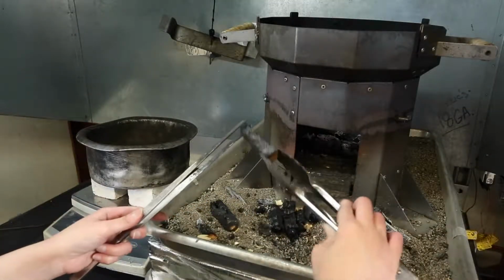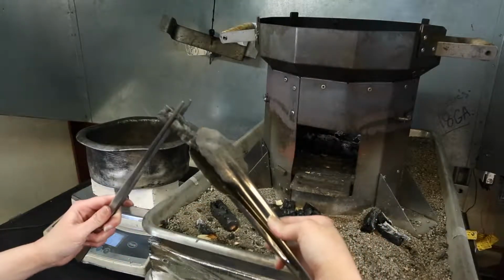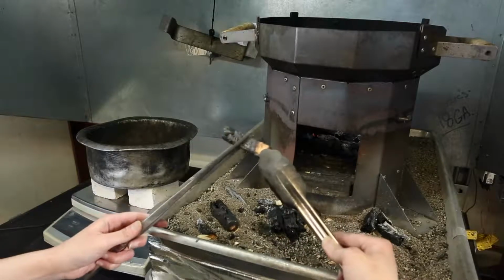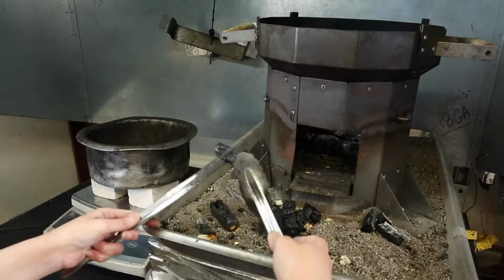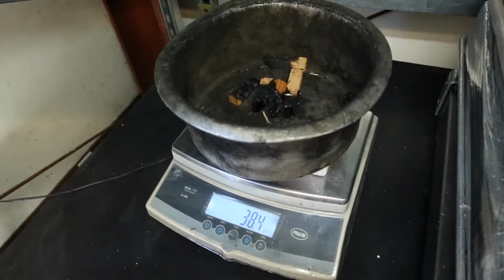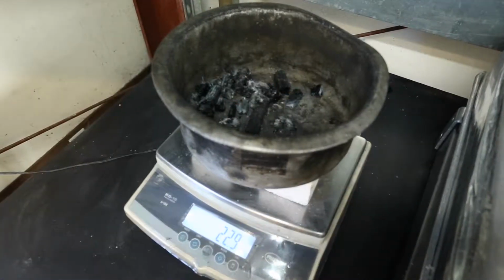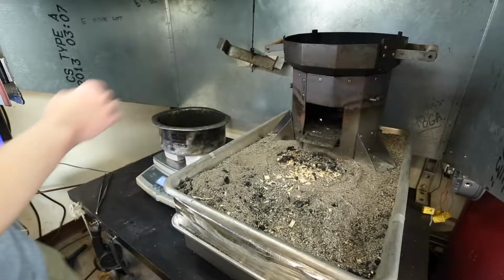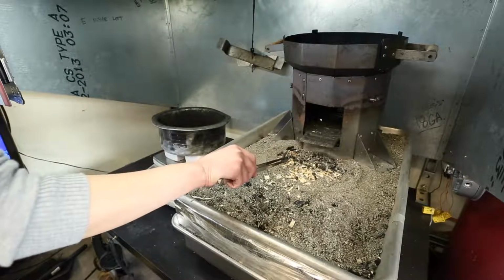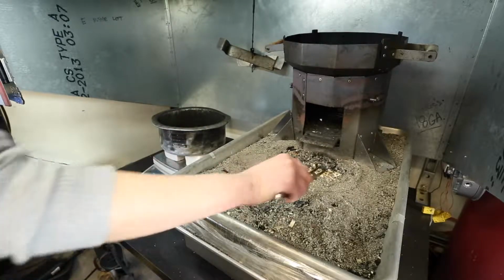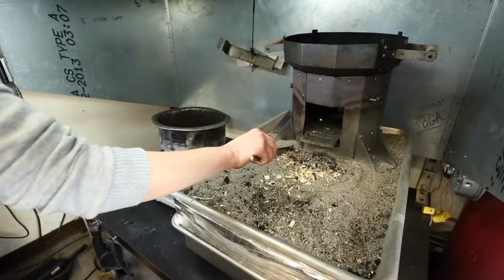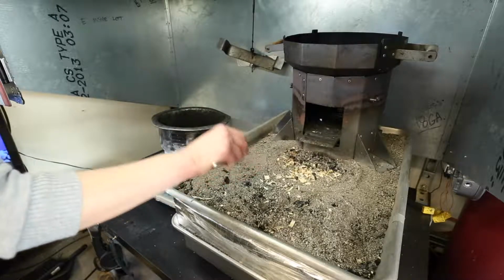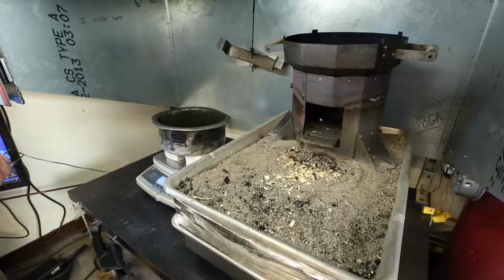Once the flames are out, we remove the contents of the firebox and separate any unburned wood from char, guided by visual assessments of texture and color and tactile assessments of density. Both the unburned wood and char are weighed separately. At the end of the test, we make sure to characterize the weight of the empty pot as well as the weight of any unused wood sticks. Together, all of these measurements allow us to properly characterize the initial and final weights of the fuel and water, the initial and final temperature of the water, and the moisture content of the fuel. Using these data, we can calculate important metrics for a cookstove test.